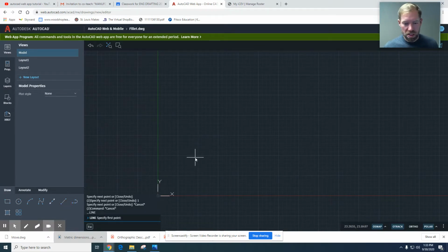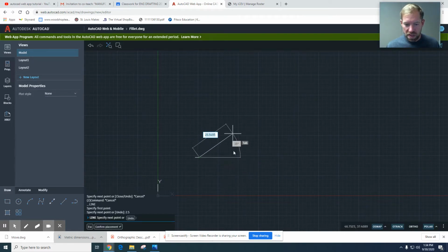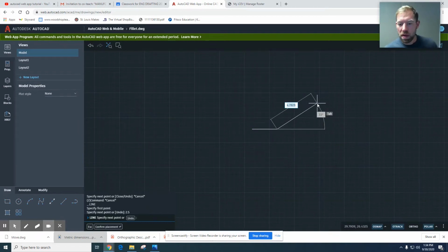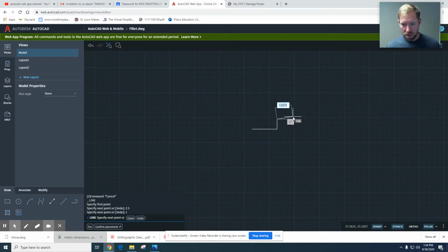I'm going to come out here into the drawing space and simply follow the dimensions that are on our example. So if I come over here and click in space and I move to the right, 2.5, and push enter, it gives me a line of 2.5. If it's kind of small, you can use your mouse wheel and wheel into it. And there you go. And then I can tell that I need to go vertical. Once again, this is the rough sketch before we modify. I'm going to go vertical for 1. I'm going to go right for 1.